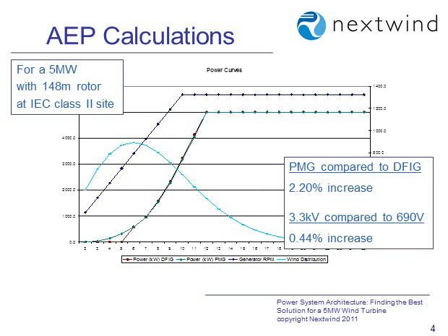The reason that partial power is important, if you look here, this is a wind speed distribution for a typical site, and this is hours here and this is wind speed, you're spending most of your operating time at partial power, so the efficiency at that partial power becomes much more critical to your annual energy production rather than the efficiency at full power.